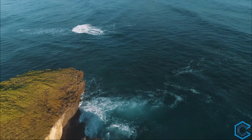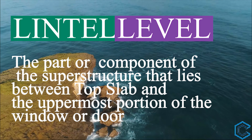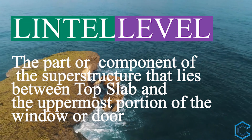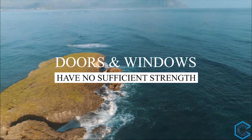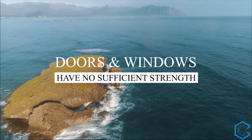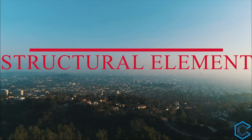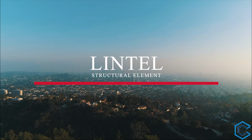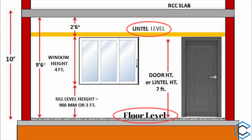Second, lintel level. It can be defined as the part or component of the superstructure that lies between top slab and the uppermost portion of the window or door. The frame of the doors and windows do not have sufficient strength to withstand the imposed load from the wall present above the doors and windows openings. Due to this, an additional new structural element has to be introduced at this level. Such a structural element is referred to as the lintel, and the level at which it is provided is known as the lintel level. The height between the floor level and lintel level is referred to as lintel height.